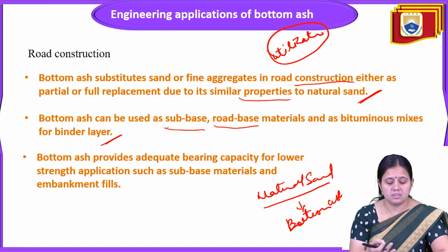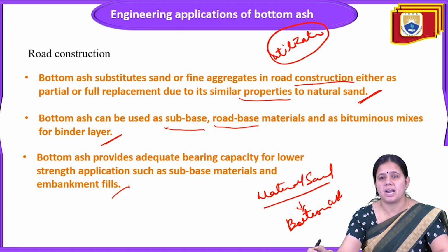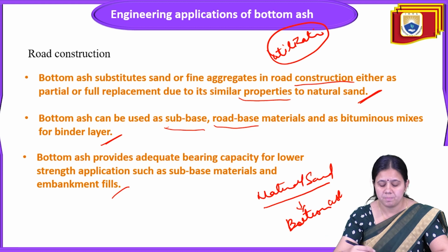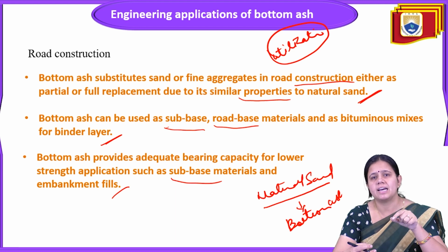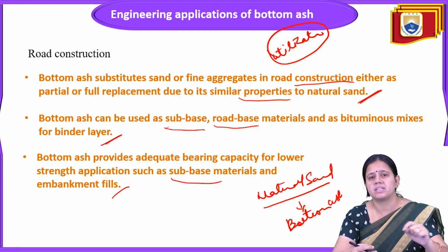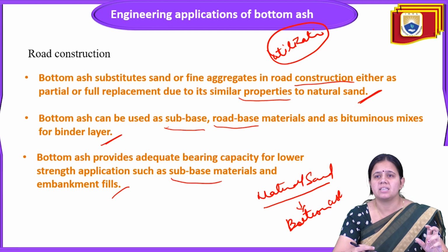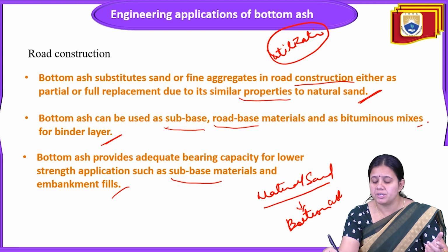And next, the bottom ash provides adequate bearing capacity for lower strength applications like sub-base materials and embankment fills. So in construction, it can be utilized as a substitute for sand or fine aggregates in road construction, and it can also be used as sub-base or road-base materials, as bituminous mixes.